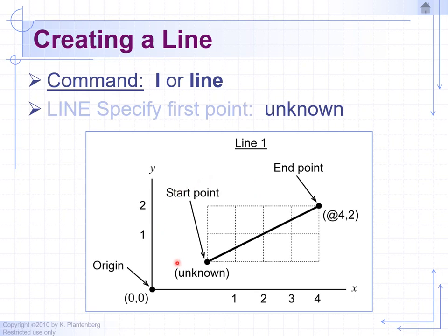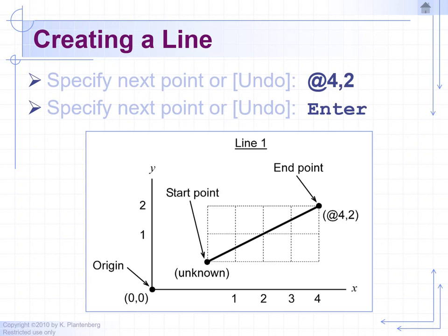So in this example, we clicked on the line icon or typed in line to create a line, and we just simply clicked in space to define our starting point. And now to locate our endpoint, to define our line, we're going to go off of our last point and not the origin. So once again, we want to locate our second point. So let's go back. We click on the line command, and with your cursor randomly click in space to locate your first endpoint.